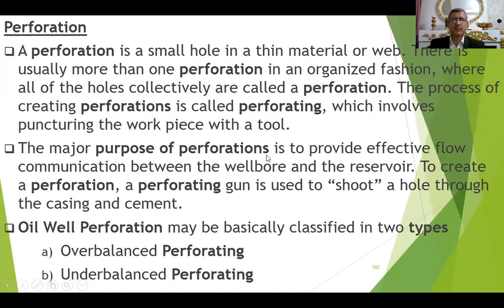The major purpose of perforation is to provide communication between the reservoir and the bottom hole or the well bore, here between the well bore and the reservoir. To create a perforation, a perforating gun is used to shoot a hole through the casing and cement.